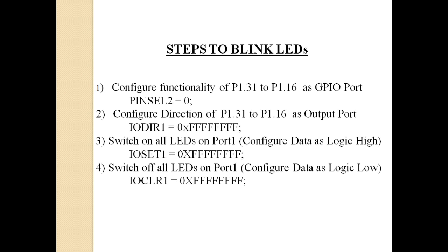So data means what? Say in my case you are connecting an LED, so you are configuring the direction as output. Then I need to make the LED on. How will you make the LED on? In that pin you need to write a logic high signal. So logic high means VCC or the supply voltage of this controller will be generated in that pin. Here LPC, all the ARM based microcontrollers, VCC is 3.3 volt. You need to keep it in mind.